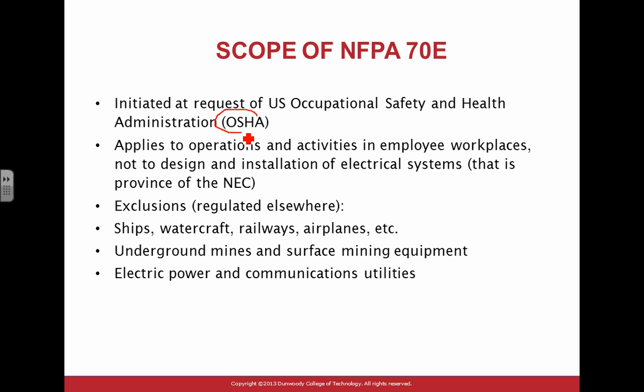So remember this one: 70E is the OSHA-adopted default standard for electrical safety. 70E applies to activities. It doesn't apply to design. It applies to working on energized equipment or putting equipment in a safe working condition.